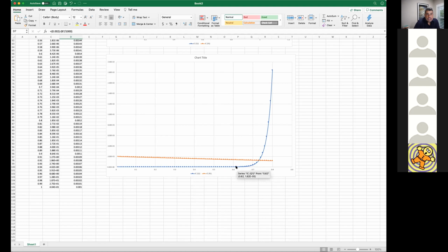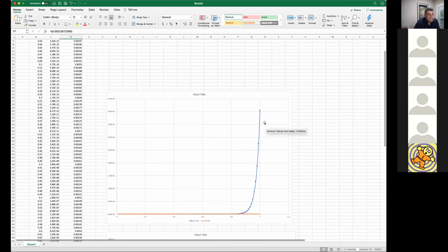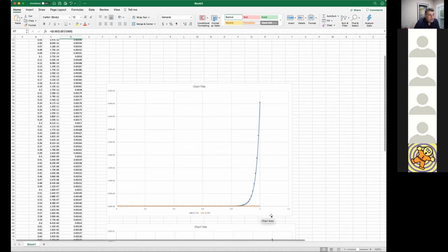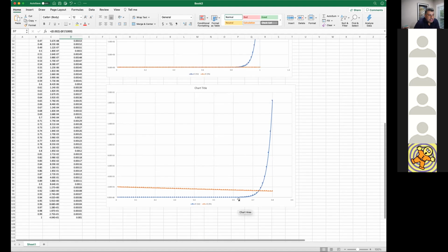It's hard to draw this exponential curve by hand to show how small the values are below 650, 600, and how huge they get past 800, 850. Again, this is exactly the same curve, just zoomed out to 1 volt, and you can see how fast this thing blows up out here. So it's really this range of VBEs that is reasonable.